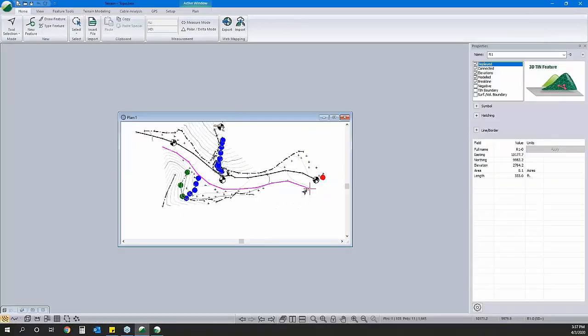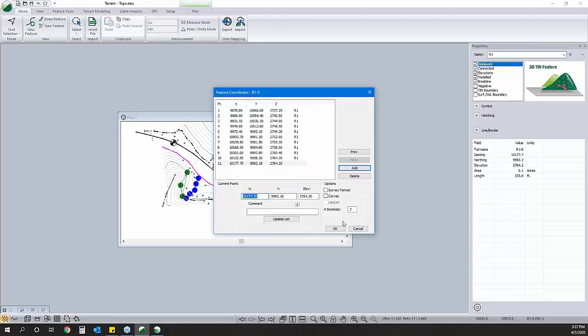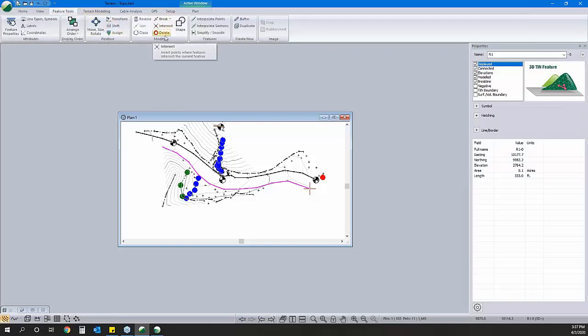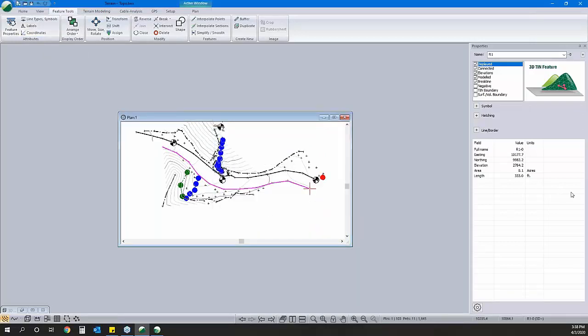Conversely, if you're adding data, and the asker kind of alluded to it as well, we can set coordinates if you're not adding new survey data in. You can set coordinates for individual points or lines by hitting Control-R. You can add those in. Control-R is the quick key for it. In feature tools, we can also go into, where is it? Coordinates. We can adjust the coordinates for points in our design file.